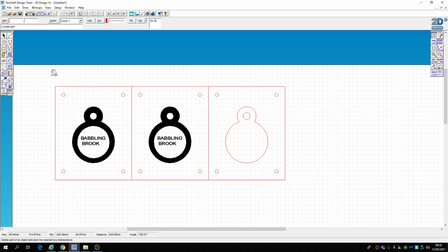Okay, so the next thing we're going to do is go onto the triangle tool, and set the grid lock back on. We know our center line is approximately there, so let's go 1, 2, 3 to the left, and then drag it back 3 to the right, and click, and we stretch a triangle up into the center.